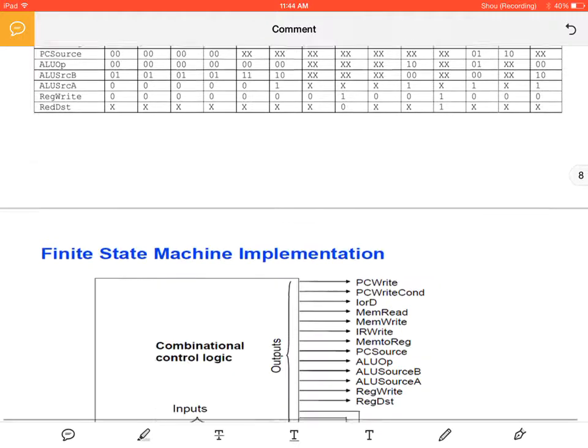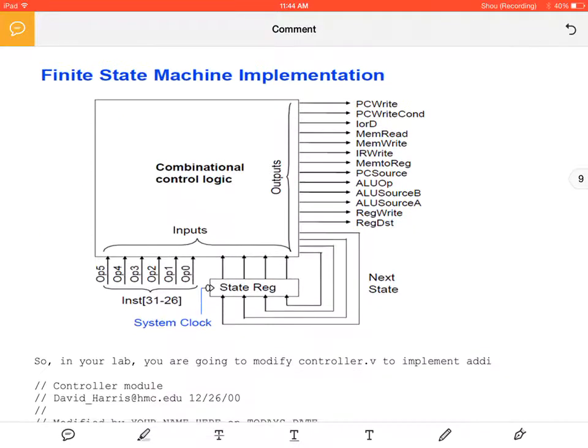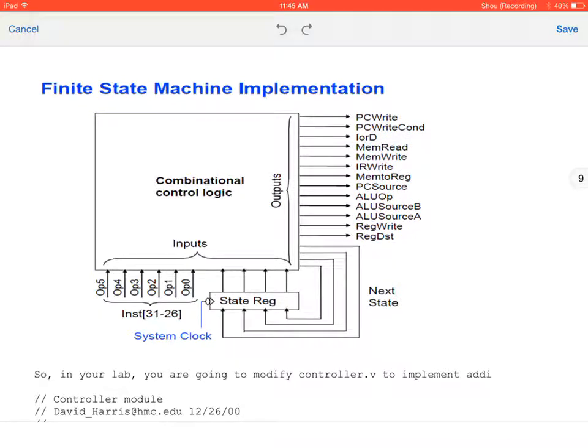All right. So, here's what is actually going on here. So you have your control logic, right? So if you recall, when you have your finite state machine, you have some sort of input set, you have some sort of output set, and you have your current state registers, right? So the state of the register plus the input contributes to the output. So what type of state machine is this? Is it a Mealy or a Moore machine?